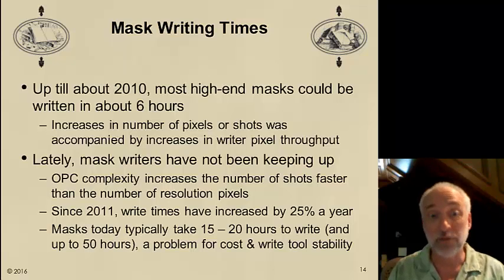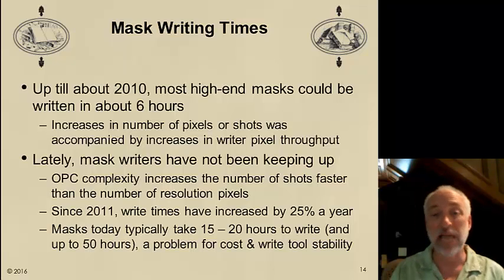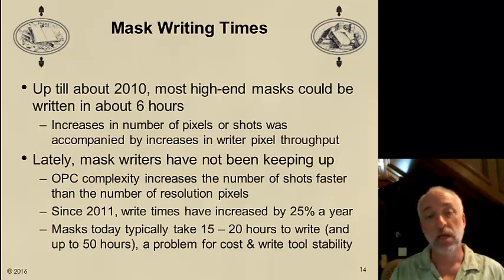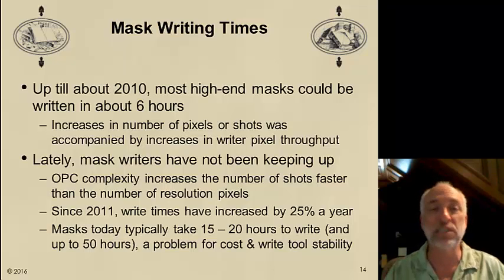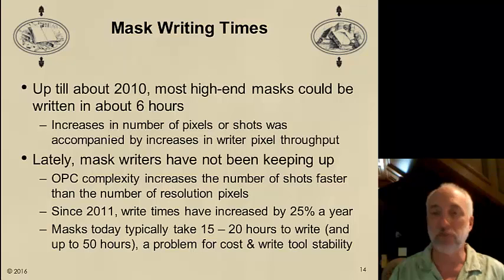And in fact, I've even heard of masks that require 70 hours. That's 3 days to write a mask. This is a problem. It's a problem for cost. The longer it takes to write, the more costly it is. But we also have to worry about the stability of the tool. Can the tool stay stable as it's writing over such a long period of time? If a tool can write for 1 week before it fails on average, well, how many times will it have a problem with a 70-hour write time? This is a big deal.